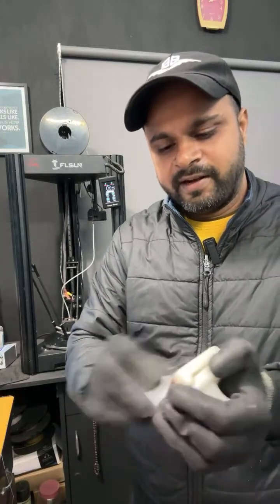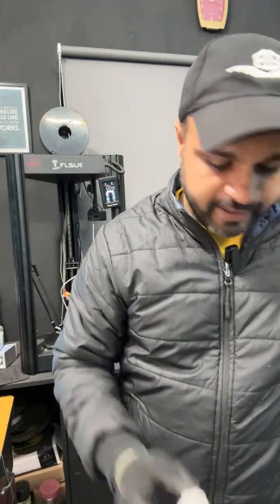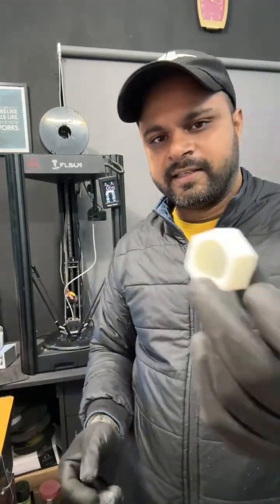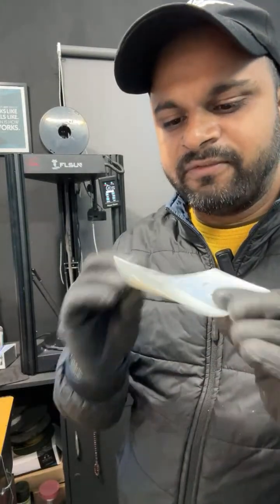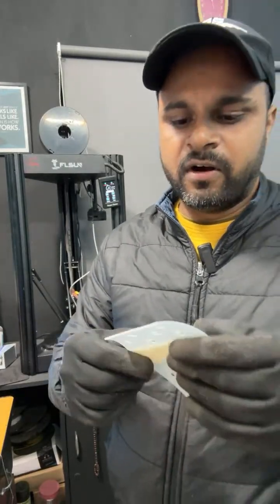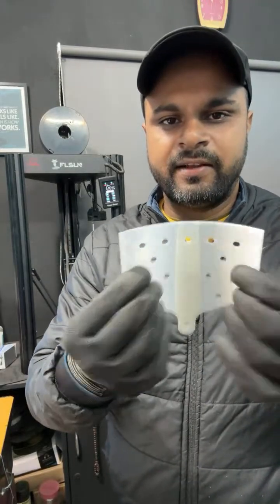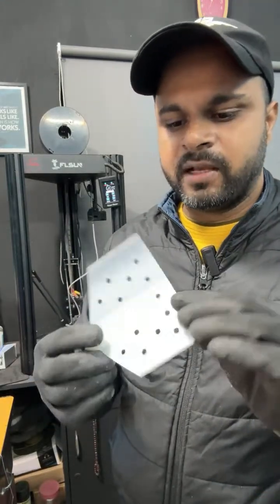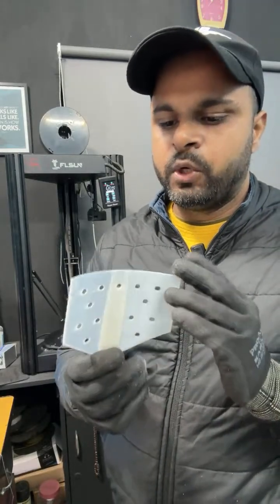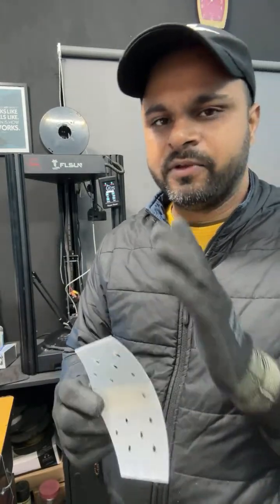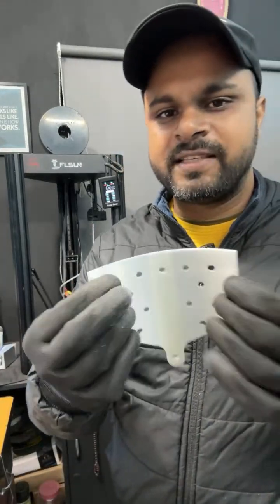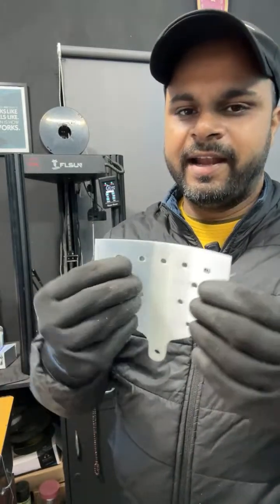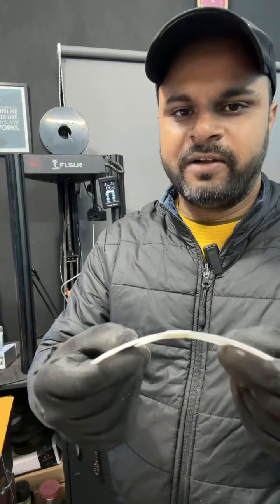So you can see whenever I rub it, yeah, and again one more done. There you can see this is my finished part. I did lots of things, like one of the parts that I had already posted a video about. Here you can see this is a flap valve, right? Not a valve actually, it's a flap. Here you can see it's flexible, because I used only two layers of 3D printing over here. Since I'm using a nozzle of 0.4 millimeter, the thickness of this piece is just 0.8, less than 1 millimeter, and that's why you can notice it's a little bit flexible, right?